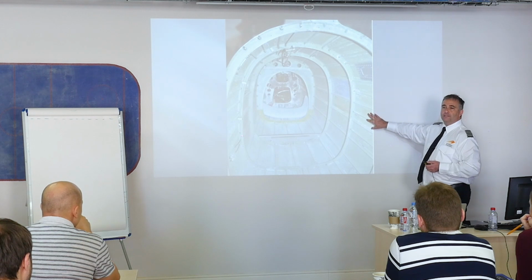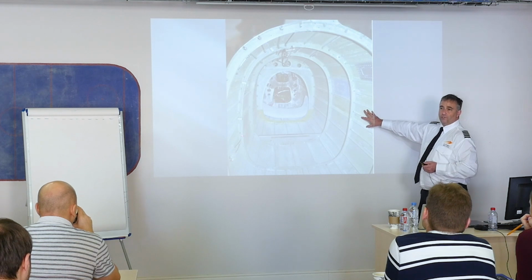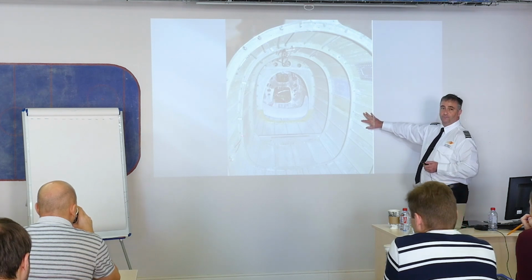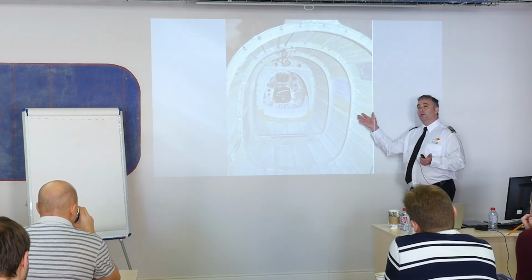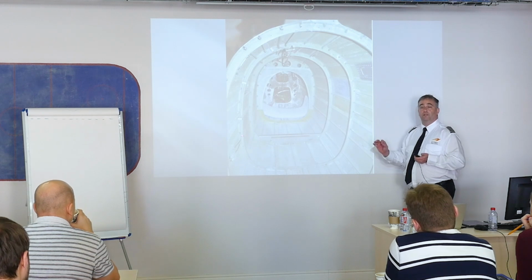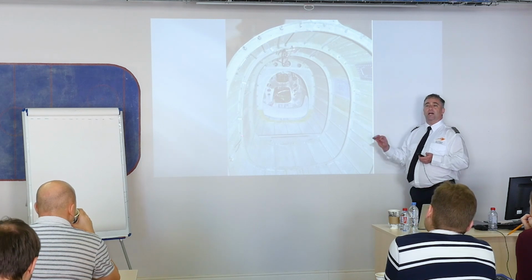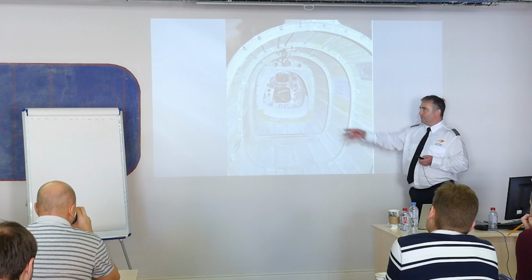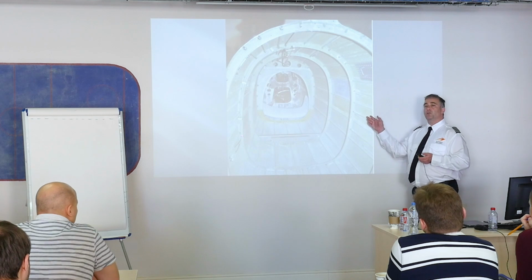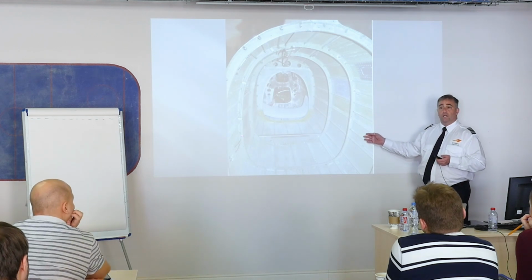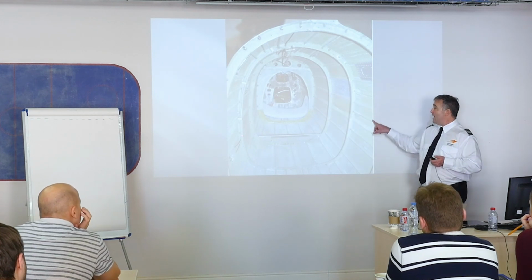Now, each one of these increases the rigidity of that fuselage, increases the rigidity of that airplane. A little bit of extra weight, it's all sheet metal, so either aluminum or sheet metal, so still very, very lightweight. But each one of these has a little bit of extra weight, and this is what's called a semi-monocoque design airplane, which, if you remember when we first went through the key terms, they had monocoque and semi-monocoque. So this is called a semi-monocoque airplane. If it were a monocoque airplane, it would not have these longerons and not have the stringers.